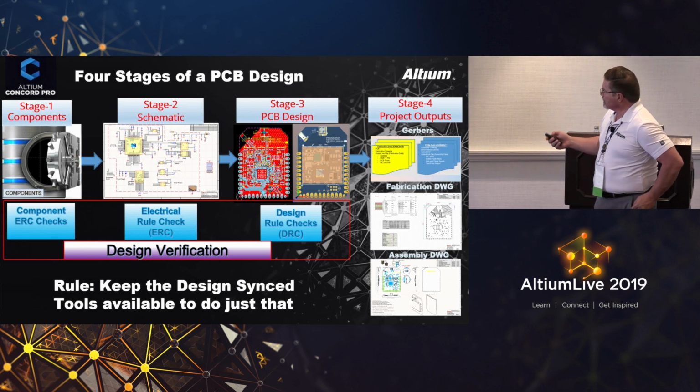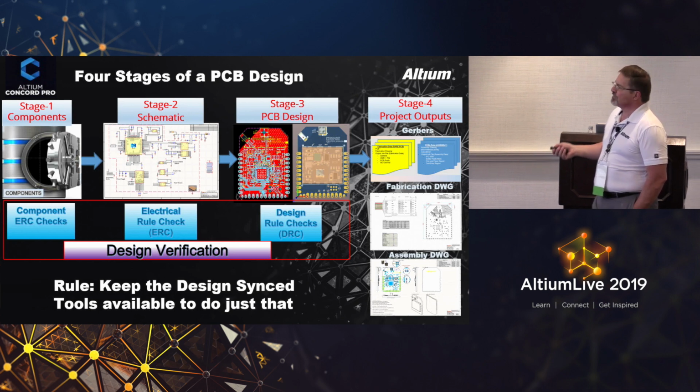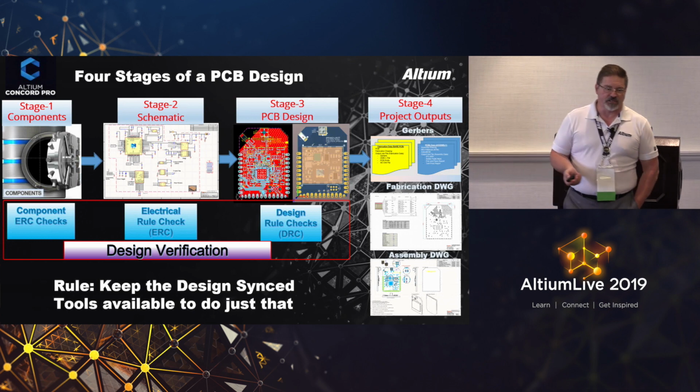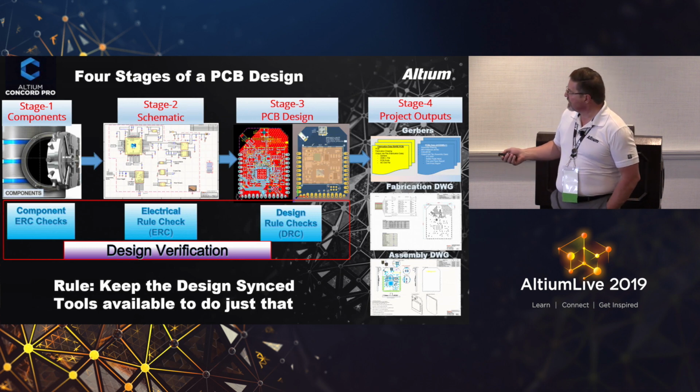So there are 3 different stages of design verification that you have: for your library, your schematic, and your DRCs for your design, your PCB itself. Always verify those designs at each of these stages.